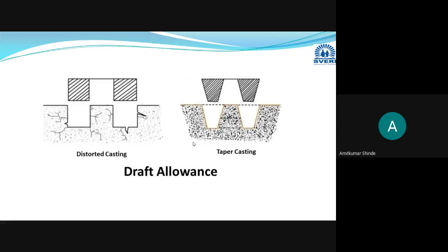From the next session, we will start the design related considerations. Already we have discussed the concept of minimum wall thickness. Wall thickness is the most important aspect in the designing of the plastic part. From the next session, we will discuss how, while designing the ribs, why ribs are provided, and how you have to decide their dimensions, then coring, then corners.